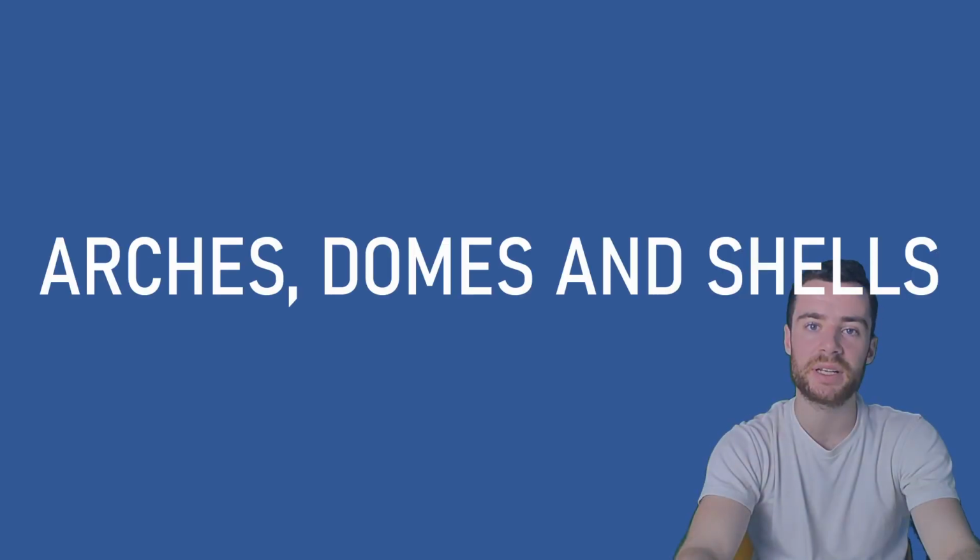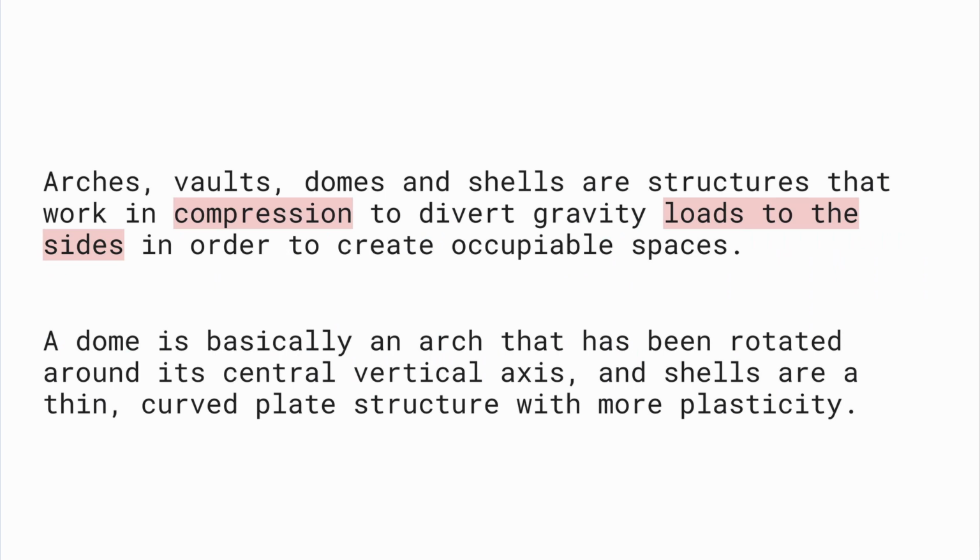Now to our final category, arches, domes and shells. Arches, domes, shells, and even vaults are structures that work in compression to divert gravity load to the sides in order to create occupiable spaces. A dome is basically an arch that's been rotated around its central vertical axis, and shells are a thin curved plate structure with a bit more plasticity.